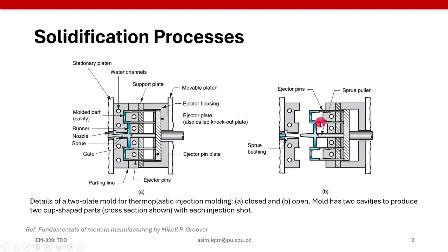In this figure you can clearly see the output is not a net shape, it is a near net shape output, which means we need to remove this sprue and runner from our final product. So design is primarily important with respect to our course, how this tooling helps us to create the final product, and definitely with this design we have to spend some time. So with respect to time and productivity requirements, you have to look at these factors.